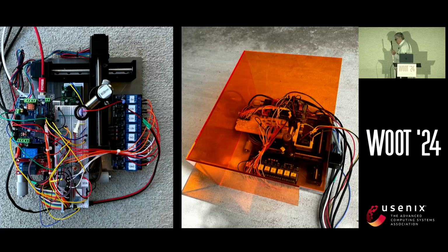Each linear actuator has a stepper motor on it, and there's a bank of relays that lets us automatically vary the bus voltage and the pull-up resistor value, so we can simulate all kinds of different circuits. The orange stuff is radiation shielding. Data collection is automatic, transmitted out by a serial connection. The whole thing is controlled by an Arduino. I like Arduinos. It's all C++. The hardware is relatively hard to accidentally fry, and they're cheap.